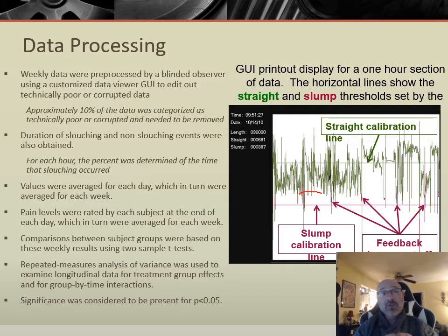So that's where we talked about how we vary our input functions. The way we varied our input functions was we set blocks with set amounts of curvature on our flex sensor, and that was our standard input. And we looked at it and said, okay, if this is sitting still and we know the curve is this, why is our data all over the place? What is this disturbance that we're seeing in here? So that's a real life application of how important it is and how difficult it can be to determine that D of S within our control system.